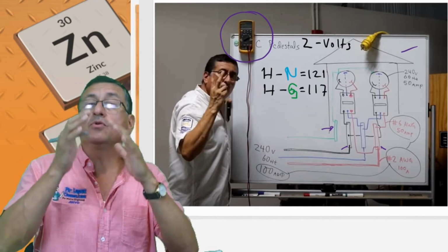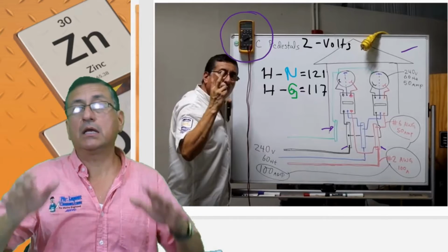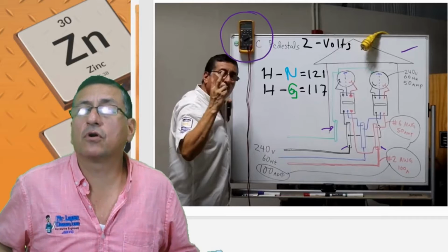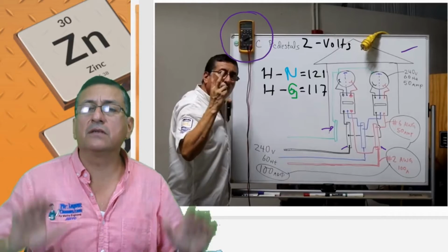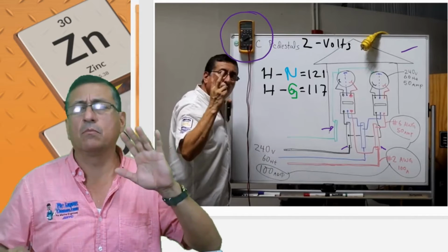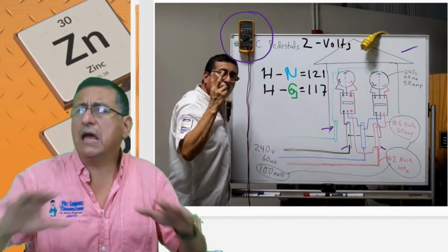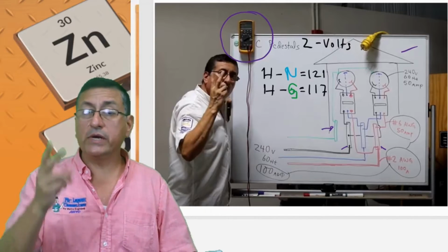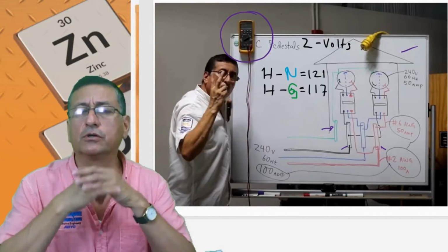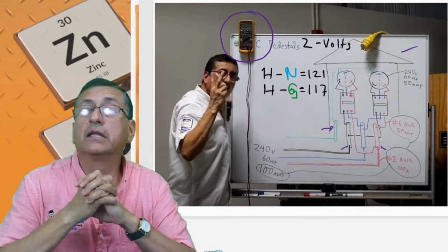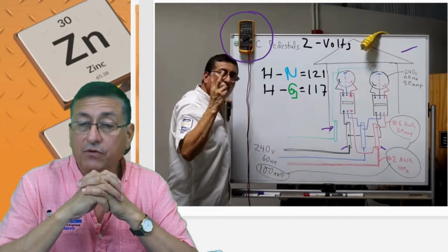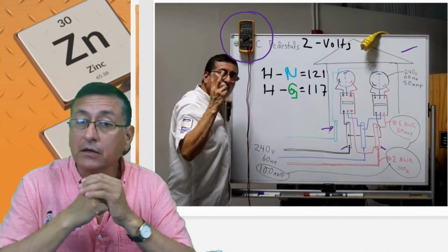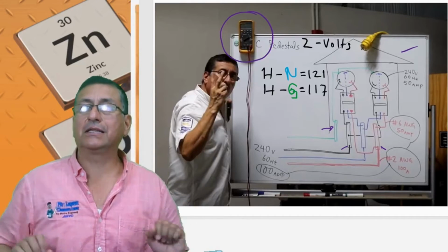Explain to him that when your boat is normally docked in your home, you don't have problems of corrosion. Your boat is clean inside. All the blocks, the motor, generators, the air conditioning equipment, everything is clean. But you moved your boat to the marina 2 weeks ago, and right now everything is corroded. And you check the ground in the pedestal, and you found that difference, more than 2 volts. That's the reason. Alright? Okay, I hope you are clear with that concept.